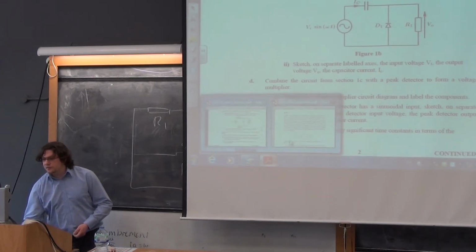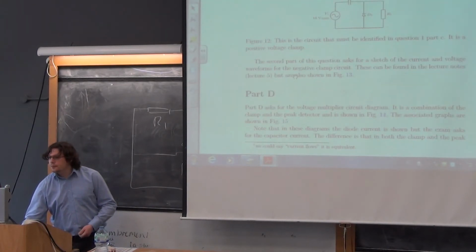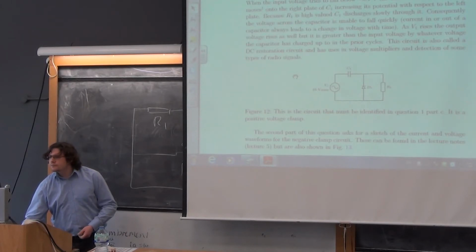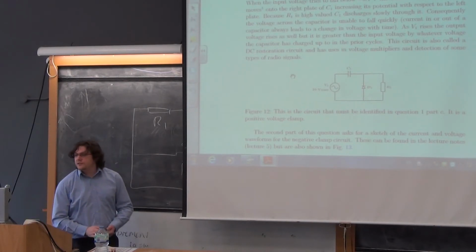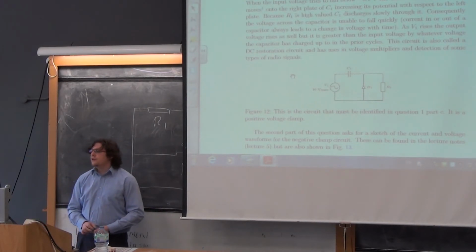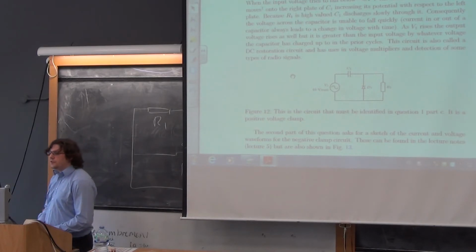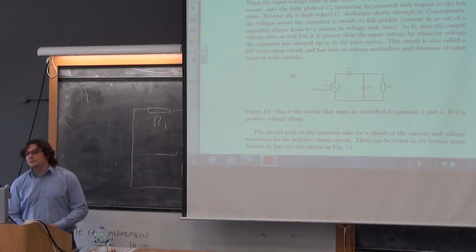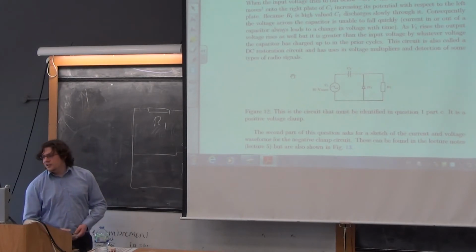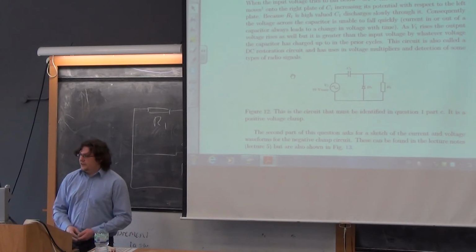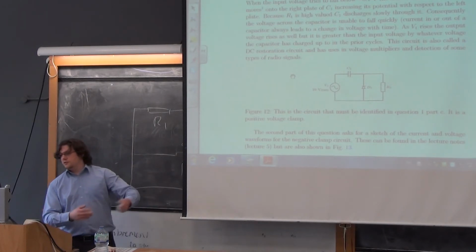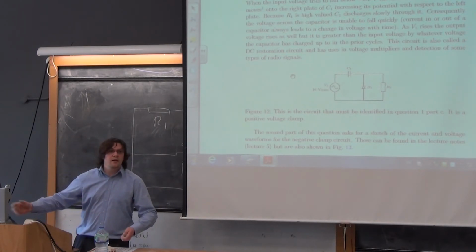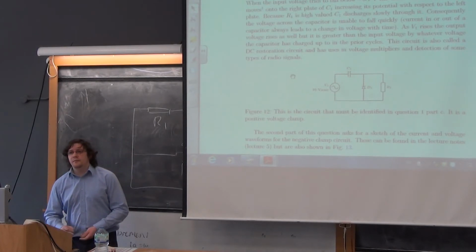So my model answer for this is, well, it's more or less what I've written in the paragraph that's on the screen now. The input voltage V1 is sinusoidal and centered on 0, and the output voltage Vout is taken across R1, and the minimum is minus 0.7. When the input tries to fall below minus 0.7 volts, then the diode conducts and the charge moves onto the right plate of C1, and so on. And you have to just go along like that.